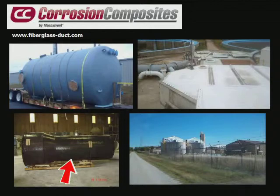That happens to be the big culprit there: sulfuric acid that's reaching its dew point due to the moisture and the temperature change. And what we've made that with is a high temperature vinyl ester resin. It has a heat distortion temperature of 470 degrees. And it's also filled with carbon. It has a carbon veil, and it has carbon graphite powder throughout it. So that's an unusual piece.